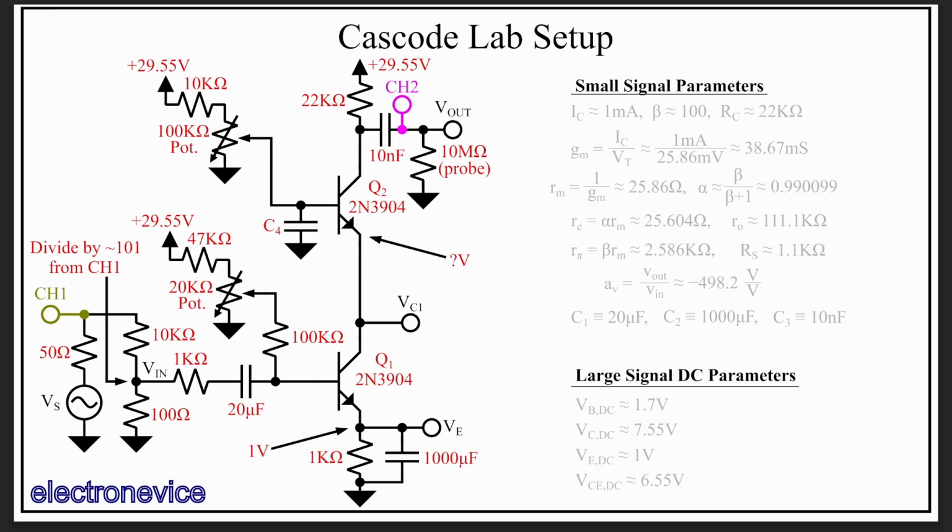So if we recall, in order to keep a BJT solidly in the forward active region, we decided that a collector emitter voltage of 3 volts or higher is our target value. So we left 3 volts for the common base when we designed the biasing for the common emitter. Now it's time to set the biasing voltages so that we have 3 volts across both collector-emitter node pairs. Firstly, we can keep the Q1 emitter at 1 volt, as that keeps our collector current what it was before. This also means the base voltage is the same as it was before.